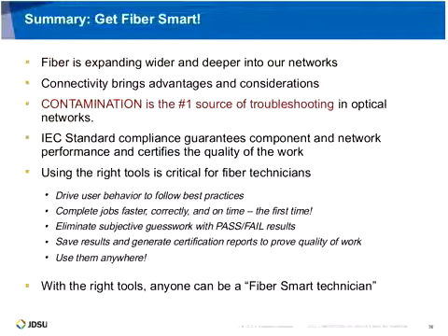But depending on the connector and the fiber type, it really depends on the attributes of the fiber. I've noticed that sometimes the core is more illuminated than other times. I've even seen this on a patch cord where you may not see an illuminated core. But the important thing is that when you're inspecting a fiber, seeing the illuminated core isn't really as critical. Where it does become more of an issue is when you're trying to adhere to the IEC standard, and this is where it becomes a challenge, because how do you know where 9 microns or 25 microns away is relative to 45 microns?